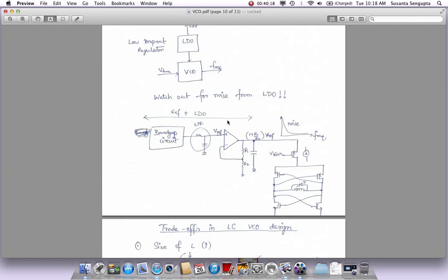But let's say even if it didn't have any junk on the VDD, what has all this done? Putting all this in is to suppress anything from VDD. But if VDD was clean, this op amp has its own thermal noise, right? There are some resistors and all, they will also generate noise. All that comes here, and as it goes through, the op amp actually amplifies it. If this point is coming from some current mirror, more like an AC ground type thing, then this has amplified all that noise.